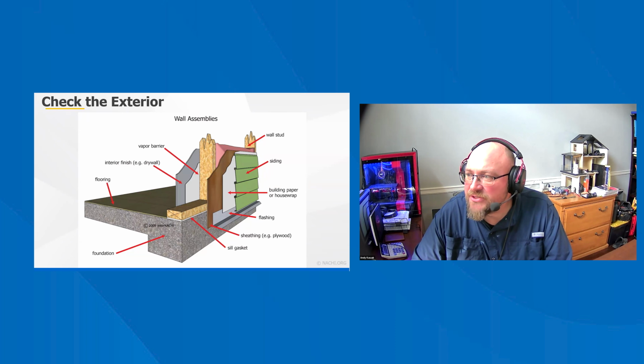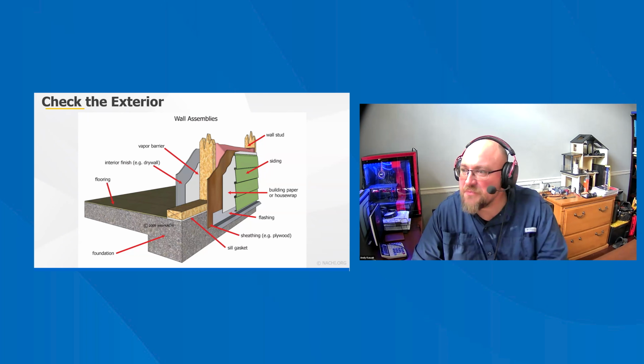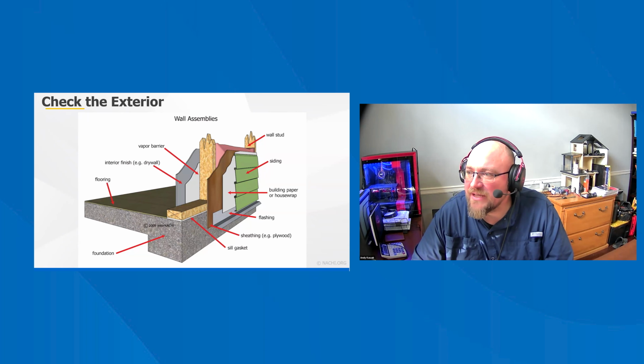Water penetration into a wall can be the result of improper installation of the siding, poor flashing installation, bad weather stripping, poor caulking around joints at the building exterior, and wind-driven rain into and through the exterior siding material. A drainage plane in the wall assembly protects against water intrusion. An effective wall has all of the following characteristics.